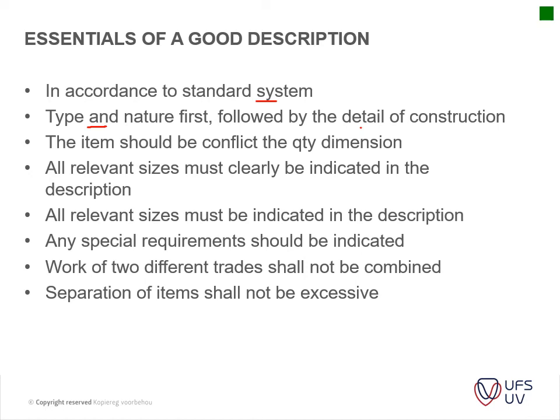Okay, and then you might add something like, usually, 2 meter by 830 millimeter door, hollow core, fitted with 3 hinges to your aluminium sash, for instance. Okay.